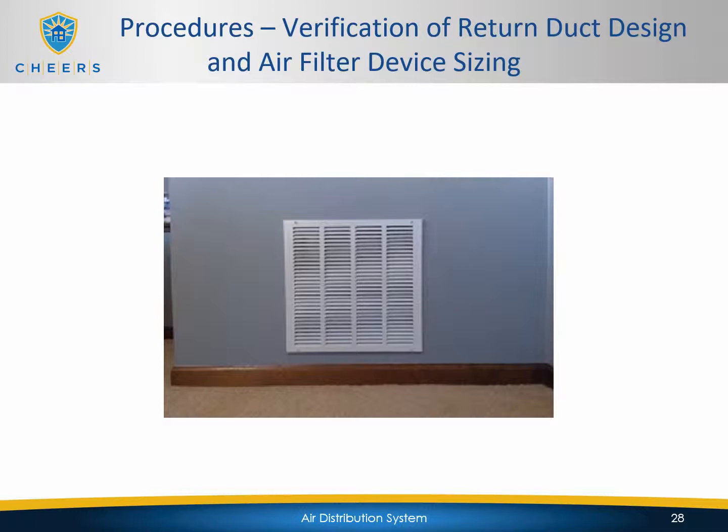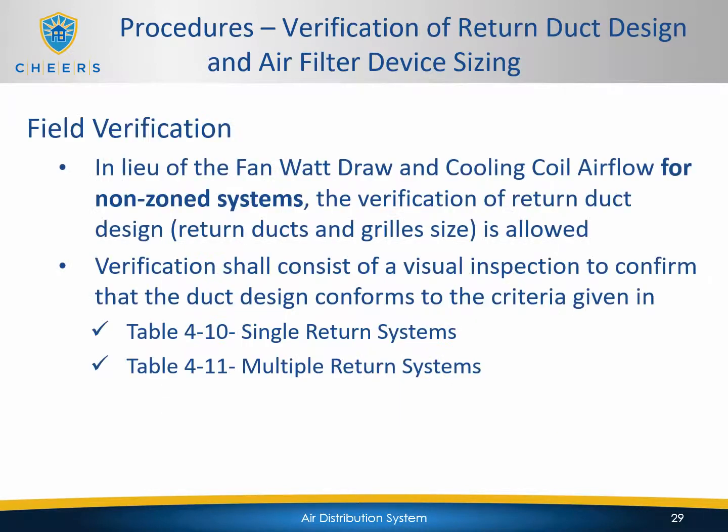Now we'll talk about the verification of return duct design. In lieu of the fan watt draw and cooling coil airflow for non-zonal systems, and non-zonal systems only, the verification of return duct design for return ducts and grille sizes is allowed. We had talked about this originally in the Title 24 overview section when we talked about the HVAC requirements. So verification shall consist of a visual inspection to confirm that the duct design conforms to the criteria given in Table 4-10 for single return systems and Table 4-11 for multiple return systems.